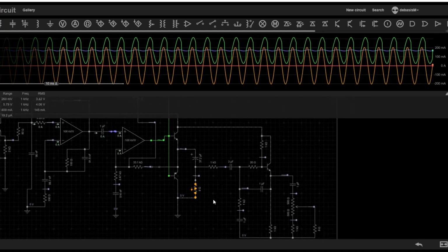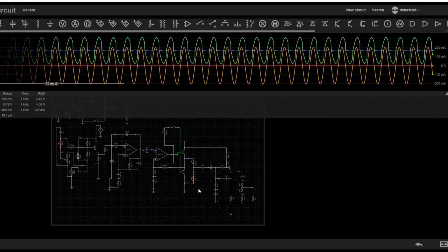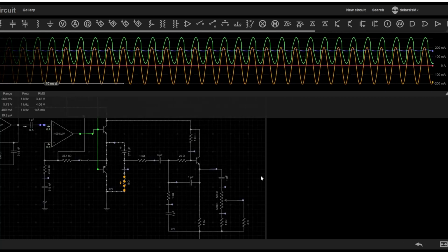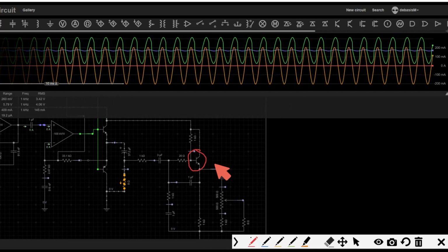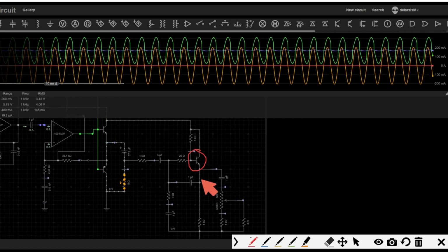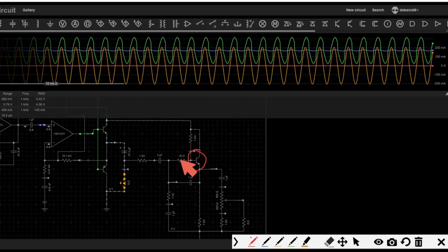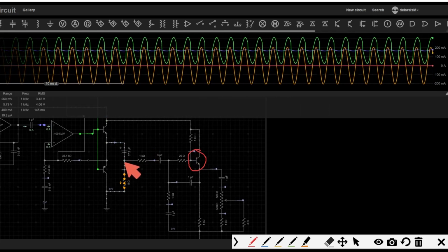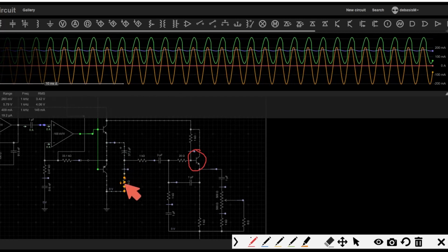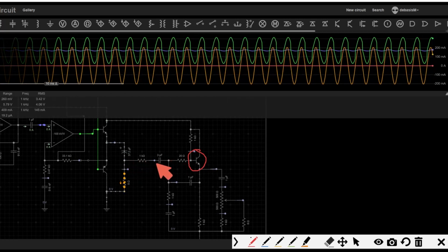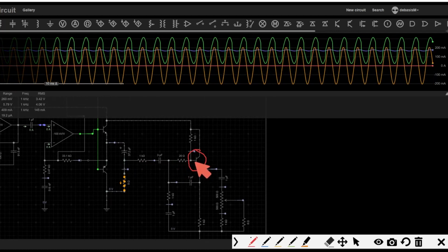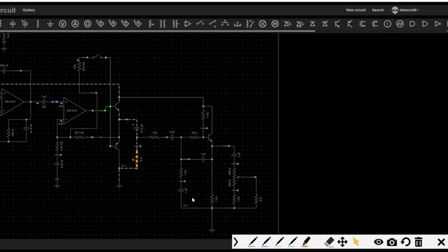Now that's not the end, friends. We have another section, the bass boosting section. Let's quickly see what's happening here. In the bass booster section you have a Q3 transistor. Let's see what it is doing. It is taking the signal from the speaker root. You have the capacitor and speaker, so the speaker is playing. From the speaker root you have resistors in series and the signal goes to the base, and you see here you have some resistor capacitor arrangement also.